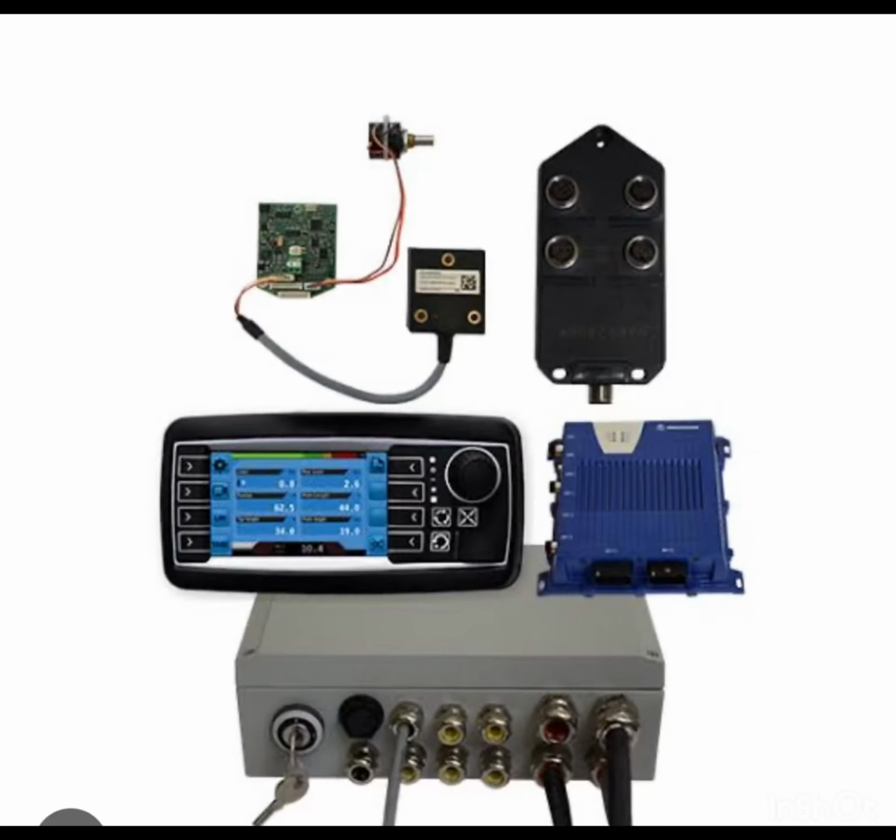What is LMI or RCL? LMI or load movement indicator, or RCL, rated capacity limiter, are safety devices used in cranes to ensure safe operation by monitoring and controlling the load. It warns the crane operator of approaching overload condition and over hoist condition that could cause damage to equipment and personnel.